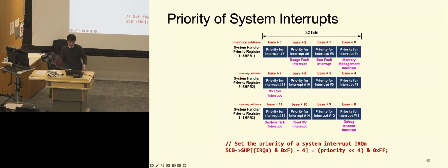Okay, so for the system interrupts, the software exceptions, etc., they have their own priority sets. Some of them you can remap their priorities. Some of them you can't, such as the three that we counted and showed before. Others, you still have the capability to change their priority values, just like the IPRs for the peripherals that we just showed.